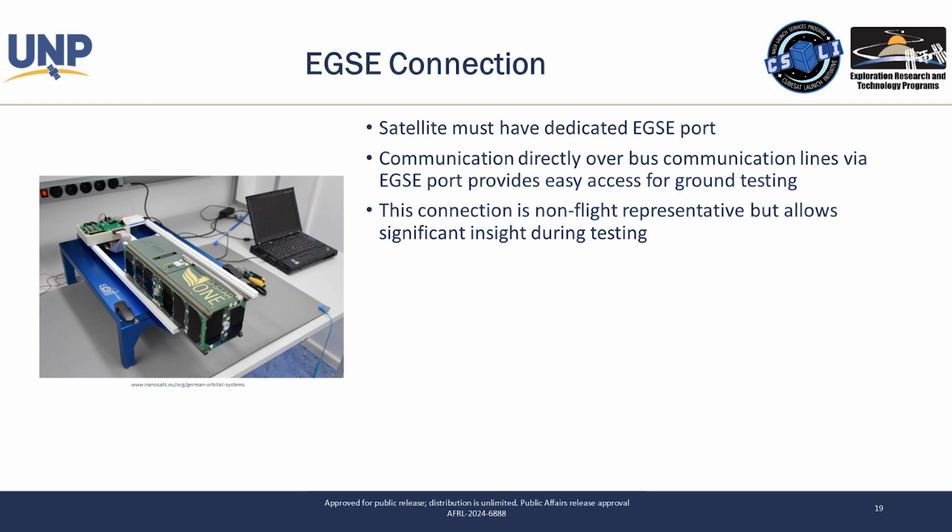Every satellite must have a dedicated electrical ground port where when it is fully integrated, you can activate the system, you can power it up, you can run your full functional tests, your abbreviated functional tests, all the way up until you are at the launch site, ready to stow it for the last time to confirm that it has survived every test, every transport, every integration activity, and is ready for a full mission success on orbit.